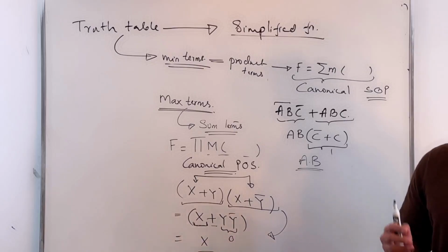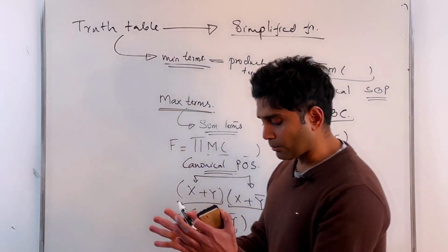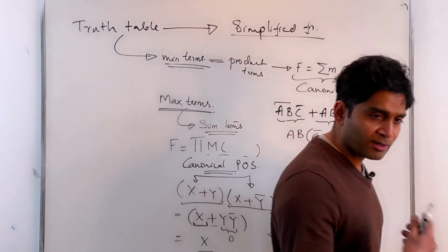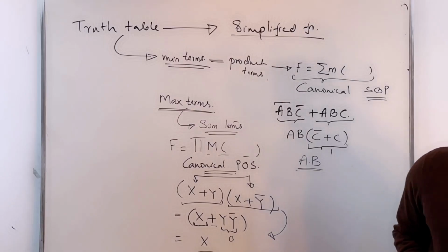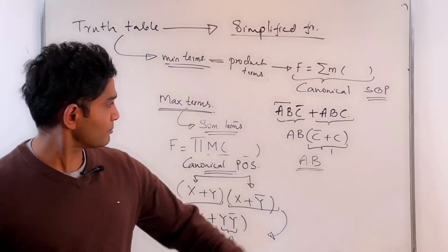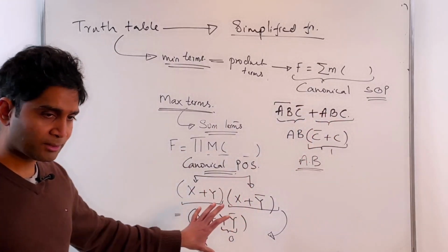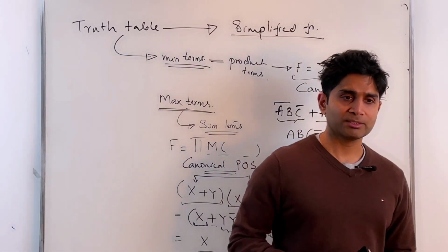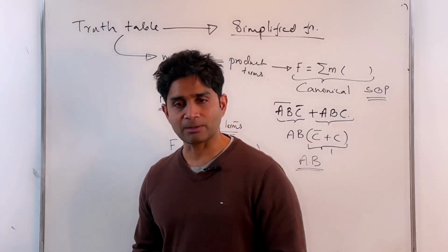All right. So you start with the truth table. I would express the function either as a product of sums expression or a sum of products expression, the canonical sum of products expression. And then I will be using my Boolean identities. Most of the time, these are the ones that we'll be using to simplify my function, to combine terms and eliminate variables from my expressions.